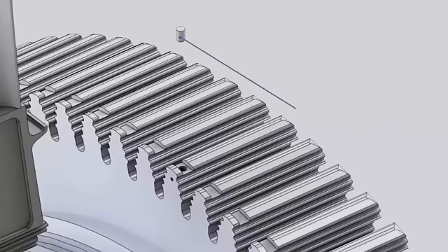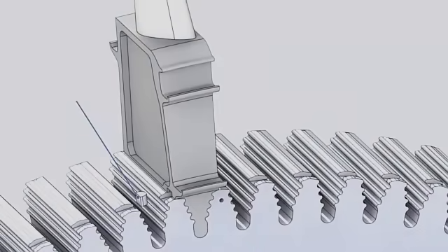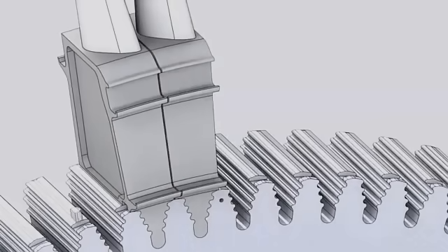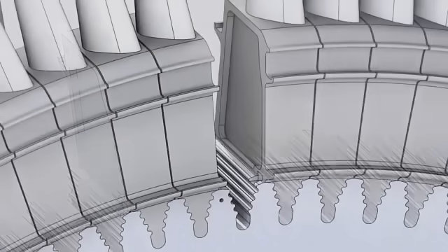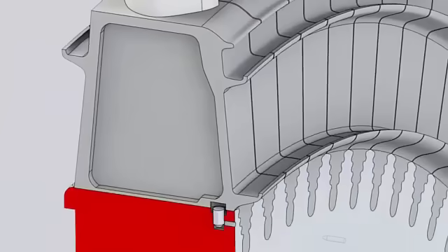A radial locking pin is installed before the first bucket. Then, the first bucket is installed and locked in place by the D-key. This is repeated for the next 90 buckets. The last bucket is installed, and an axial locking pin is inserted on the locking bucket dovetail. This pin pushes the radial locking pin to hold the last bucket in position.